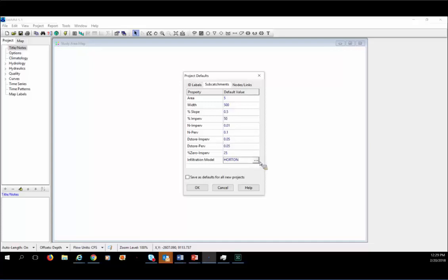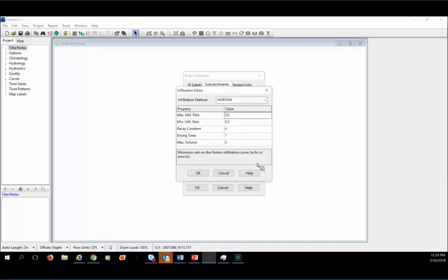As you go through different sub-catchments, it'll explain better what these specific values are. There are 5 different types of infiltration. You can do Horton, modified Horton, Green-Ampt, modified Green-Ampt, and curve number. So you can do curve number for the person who was asking about that. Most people recommend that we use Green-Ampt. And you want to have suction head, conductivity, and initial deficit. These particular values are extremely important for accurately modeling the infiltration in SWMM.